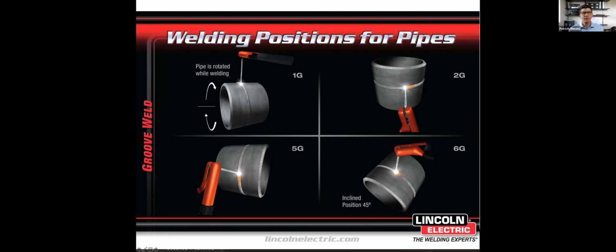In this case, 5G, right? This is the case of horizontal. And then this position, which happens in reality, but most of the time when you see welders welding in this position is because they're qualifying. If a welder qualifies to weld in this position, or with a pipe at 45 degrees, then they are qualified to weld pipe in all those other positions.